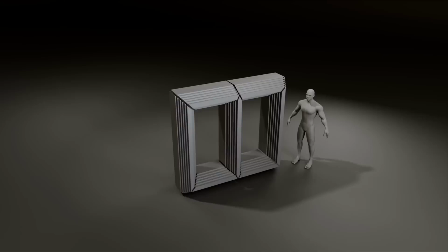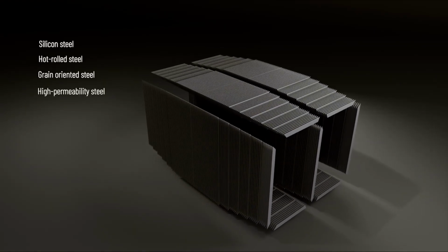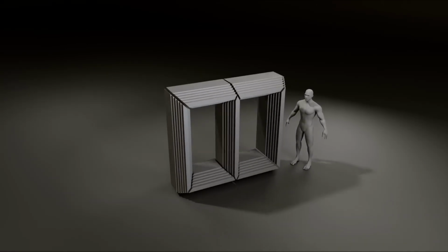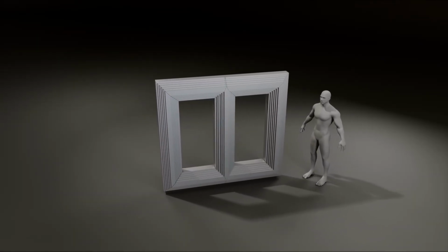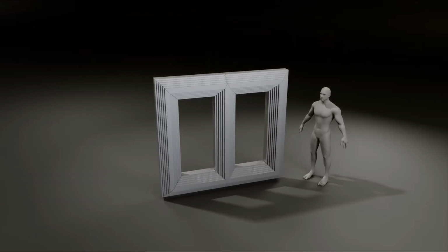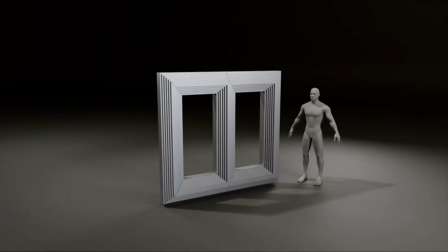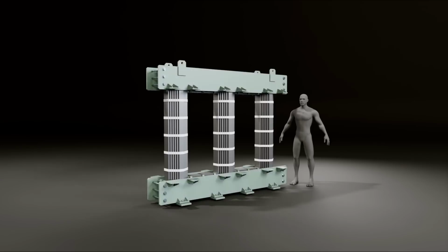A power transformer core is built from thousands of thin laminated sheets made of ferromagnetic materials like silicon steel. The purpose of the transformer core is to provide a low-reluctance path for the magnetic flux that links primary and secondary windings. The alternating flux, which links primary and secondary windings, causes vibration in the laminated sheets, generating loud, unwanted noise and leading to energy loss. To minimize these issues, the laminated sheets are tightly secured together.